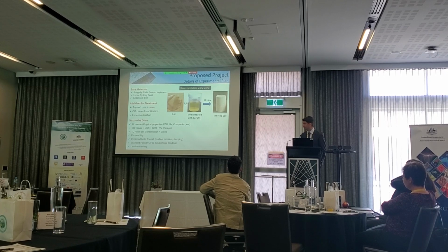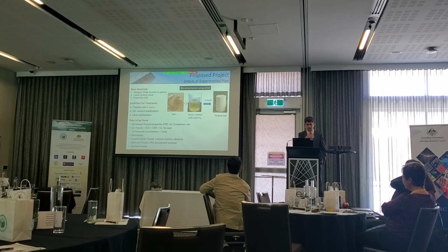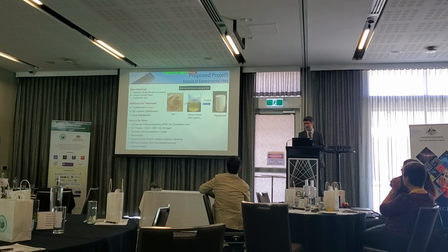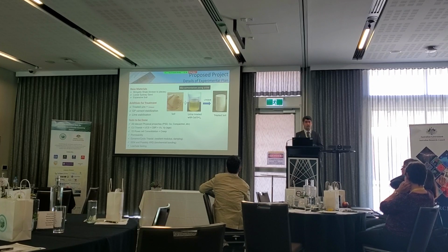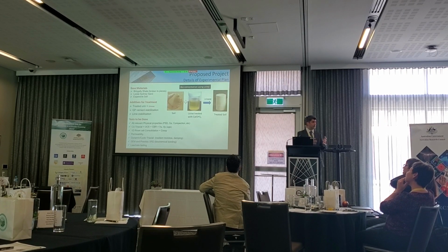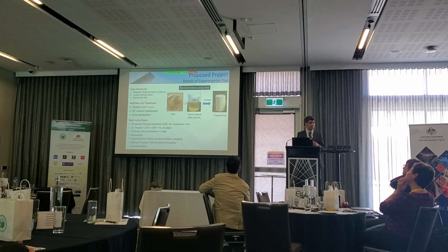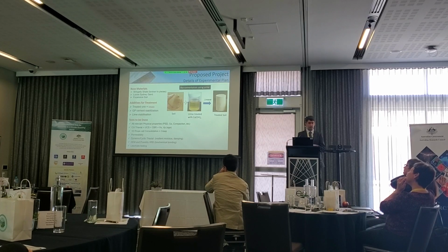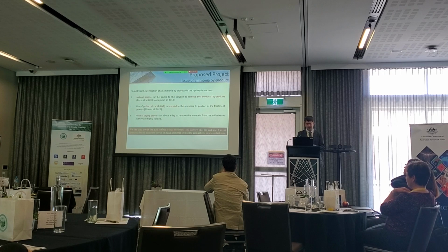And the tests that we do, again, I understand most of you apparently are not civil engineers, but we will create samples and then crush them and measure the strength of it, under different conditions required by standards for road construction. We will also do the leachate testing to make sure what goes through the groundwater flow and so on doesn't create anything that is, again, not acceptable. Permeability and so on would all be considerations for road and railway construction as well.